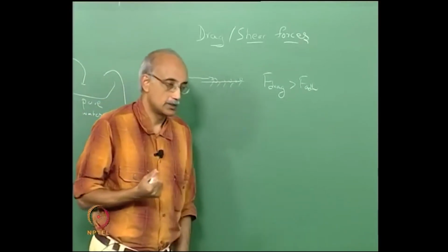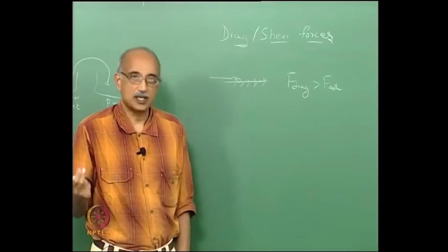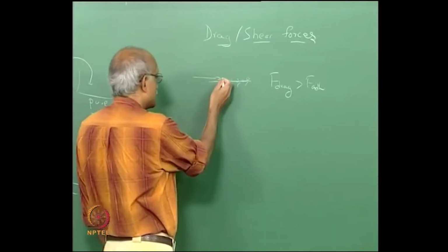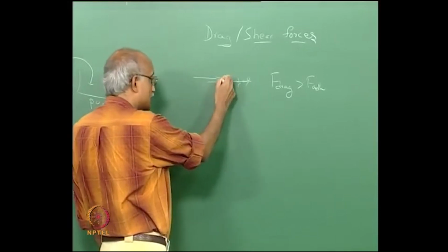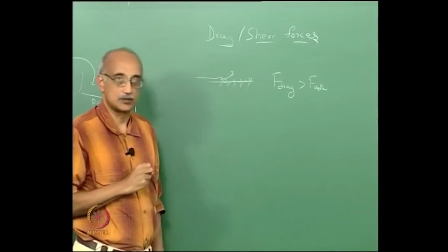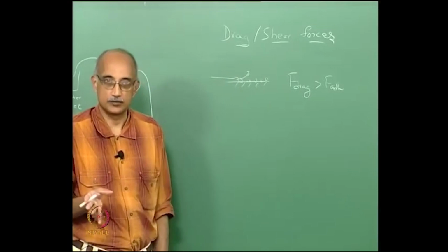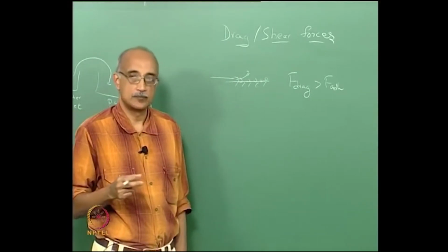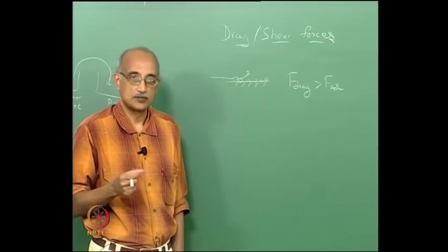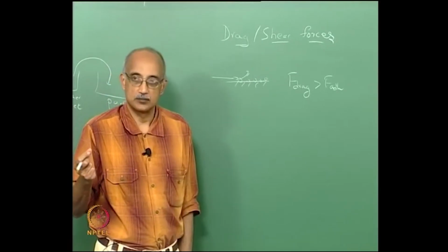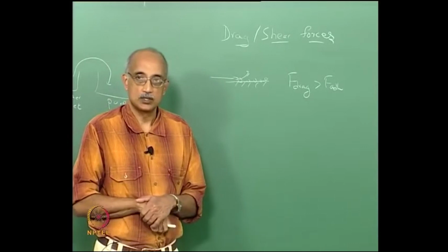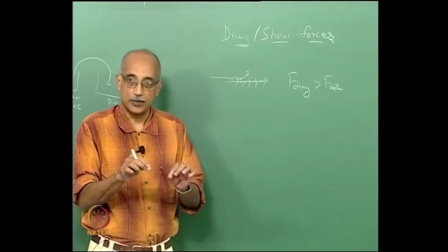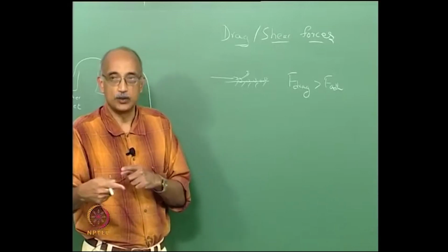but it's a necessary condition but not sufficient, because as you can imagine, when this force exceeds the adhesion force, the particle is not necessarily immediately lifted off the surface, right? It can actually roll on the surface. This rolling mechanism is something that's particularly predominant when you get finer sizes. They don't want to leave the surface, but they are being forced to. So they kind of reach a compromise and they cannot stay in the same place, so they just start rolling along the surface.